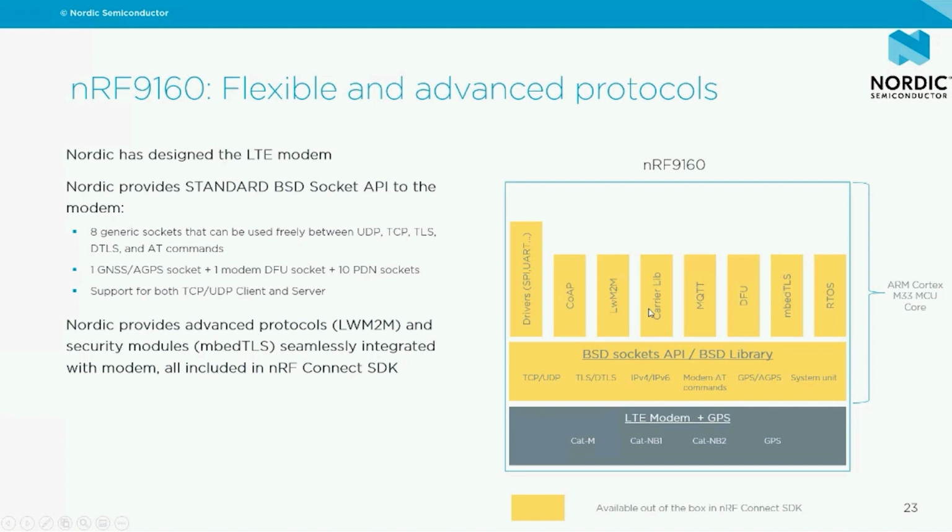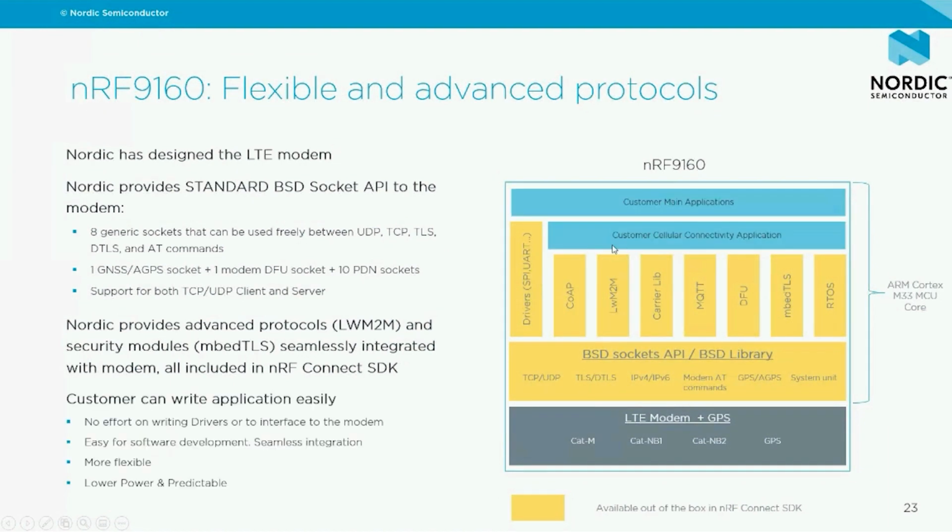On top of that, we have a lot of protocols available. So all of these are seamlessly integrated and designed together with the modem. Whether you want to run CoAP, lightweight machine-to-machine, MQTT, device firmware update, TLS, we have a real-time operating system here, and all the drivers, of course, that you need to build something. So on top of this, you can build your connectivity part, but you can also build your complete applications, meaning that you don't need to write any drivers or have any AT command interface to the modem. That's all been taken care of in the lower layers here.